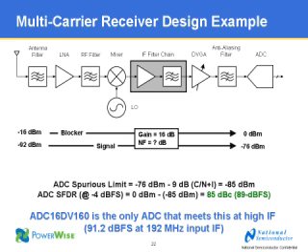All right. So now we're going to dig a little deeper and talk about the ADC criteria of performance under the blocking condition. In the blocking condition, we highlighted that we are using a gain of about 16 dB. And as Scott highlighted, we must achieve the sensitivity of minus 92 dBm. So that means that if you take minus 92 dBm at the antenna and add to it 16 dB, you end up at about minus 76 dBm.